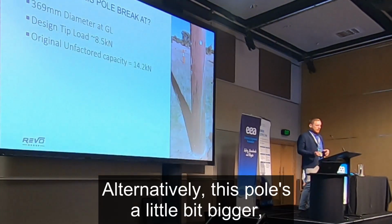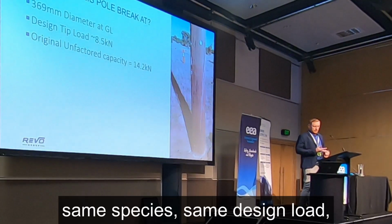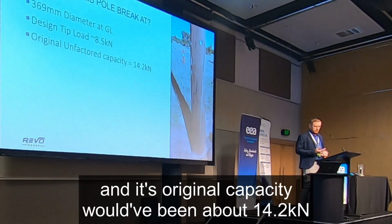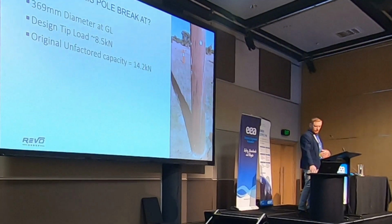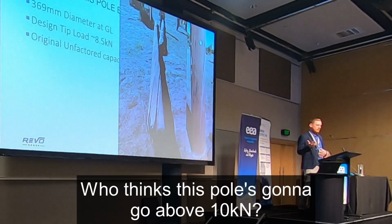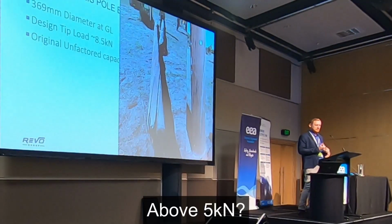Alternatively, this pole's a little bit bigger. Same species, same design mode. It's only maybe a kilometre down the road, and its original capacity would have been about 14.2. Who thinks this pole's going to go above 10 kilonewtons? Above 5 kilonewtons? Above 3 kilonewtons?